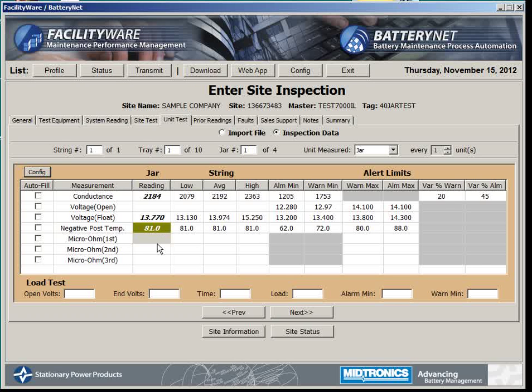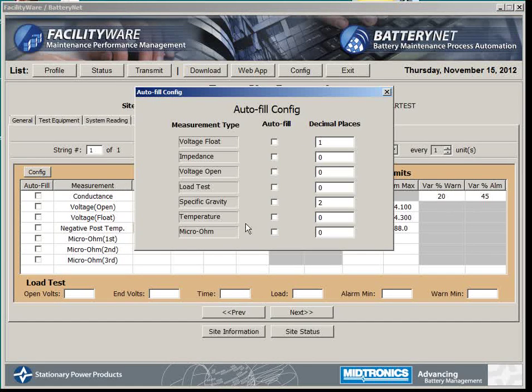You always need to enter a value. If temperature readings are 1 decimal place and you selected 1 on your temperature readings, you would have to put in a second decimal place before you could advance forward. It's not just going to copy the reading that's in there continuously to the next one. You always have to make an entry. So if there's only 1 decimal place, you would want to have this particular field 0, not to retain any decimal places.